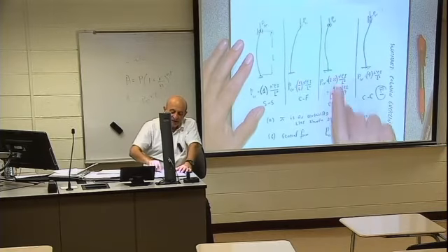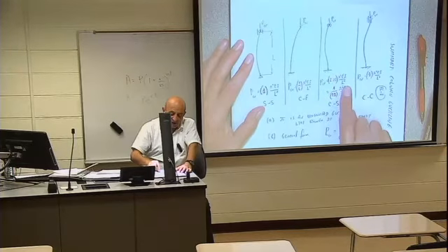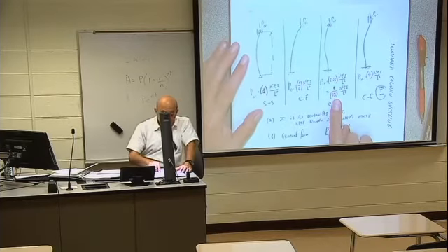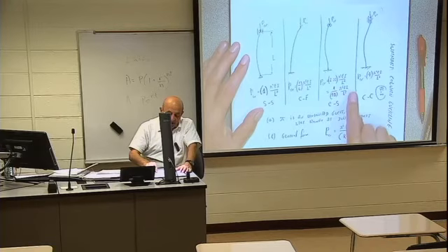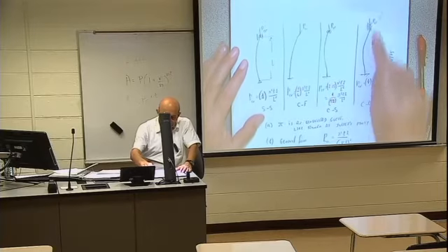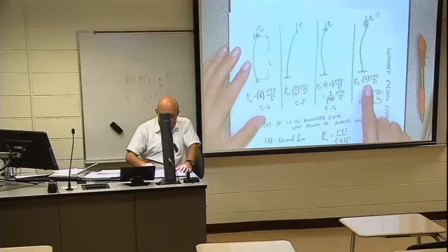Here, P critical equals approximately 2.05 pi squared EI over L squared, or approximately 1 divided by one half squared. Okay? Pi squared EI over L squared. That is clamped, simply supported. And here, clamped at both ends, we obtained a factor of 4, pi squared EI over L squared.